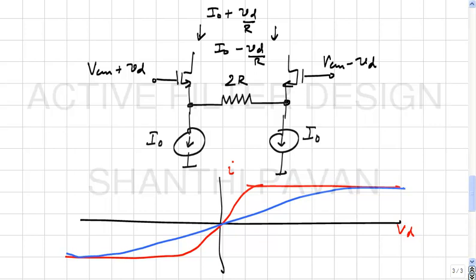All right. Now, visually it's apparent that the linear range of the transconductor is increased significantly. You can go and do the maths, and find for a given transistor overdrive and GM and so on, what is the increment in linear range. It's messy, but can be found in a quite straightforward manner.